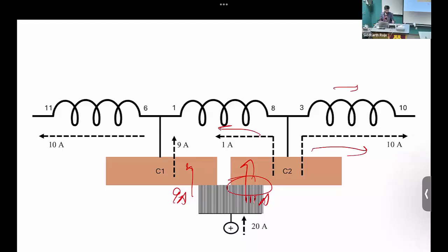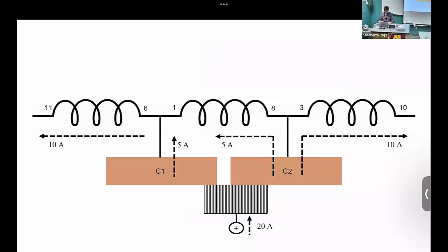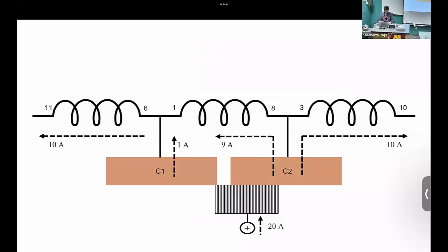1 ampere is going to start to flow into this conductor, which is shorted. If you look at it, previously this coil had the current of 10 ampere in the positive value, and then it went to negative. Now it's starting to go further negative. And the commutation would be completed once the contact is fully broken. And when the break happens, we better hope that this conductor carries 10 ampere.